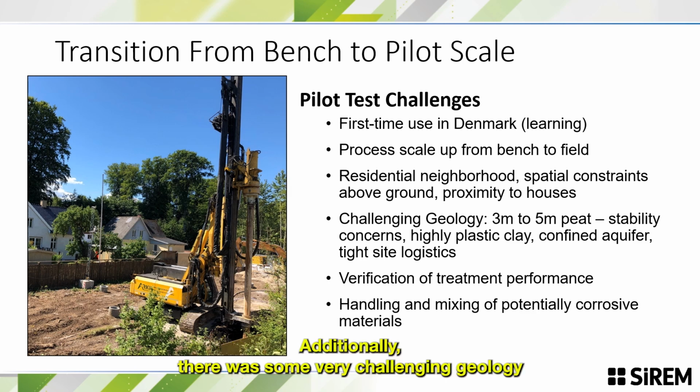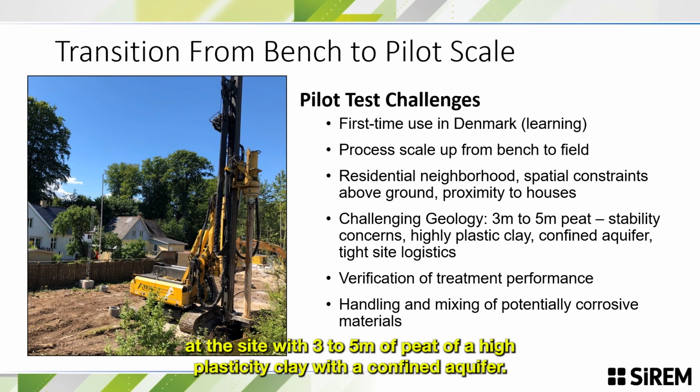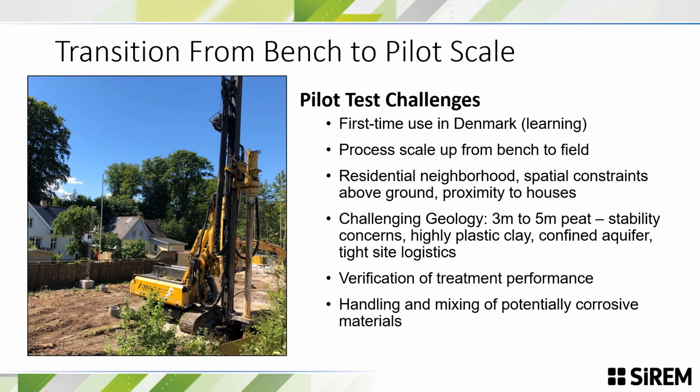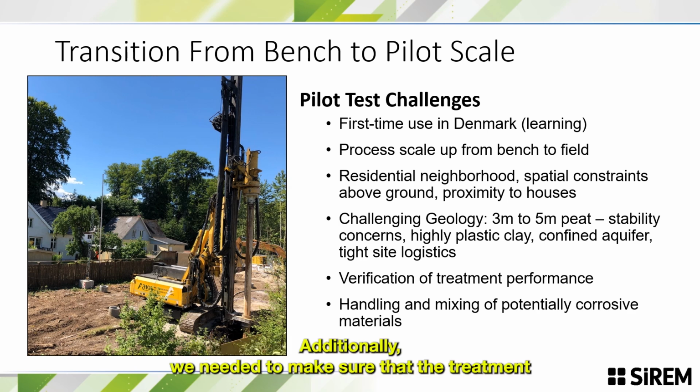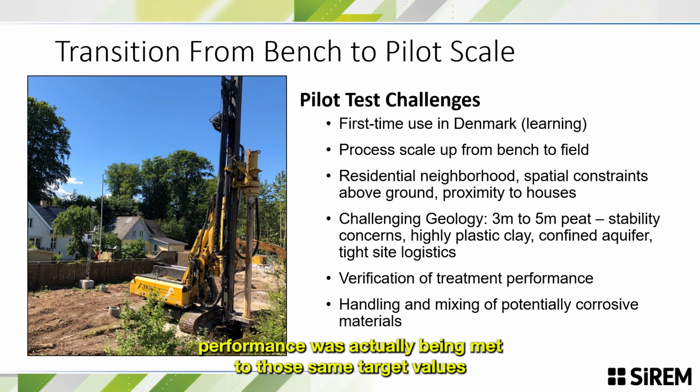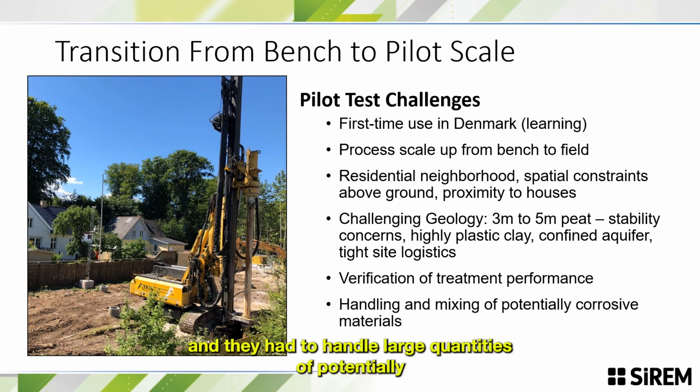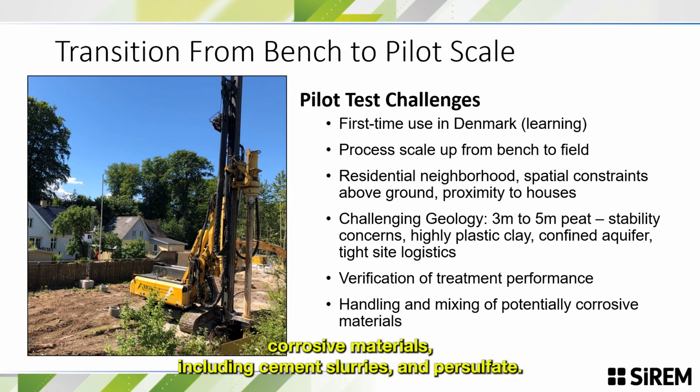Additionally, there was some very challenging geology at this site, with 3 to 5 meters of peat above high plasticity clay with a confined aquifer. Additionally, we needed to make sure that the treatment performance was actually being met to those same target values. And they had to handle large quantities of potentially corrosive materials, including cement slurries and persulfate.